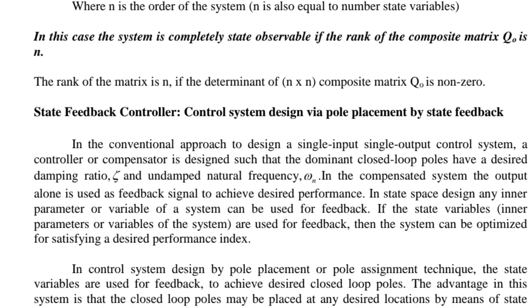Now, feedback control: the control system designed via pole placement by state feedback. In the conventional approach to designing a single input, single output control system, a controller or compensator is designed such that the dominant closed loop poles have the desired damping ratio zeta and undamped natural frequency omega n. In the compensated system, the output alone is used as the feedback signal to achieve the desired performance.